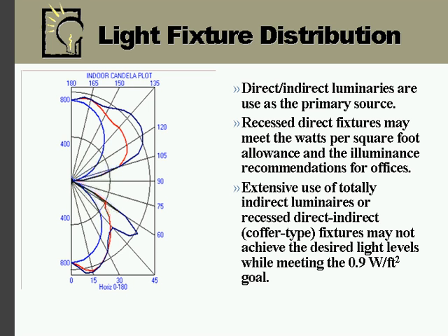And going back to the ASHRAE standards for a second here, in the models that Eric showed you, the standard fluorescent light fixture that's used is a direct, indirect fluorescent luminaire. That is the primary light source for both open office and private office. 75 to 80% of the foot candles are provided by this type of luminaire.